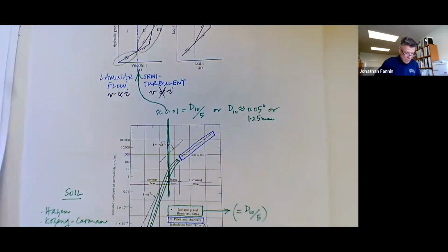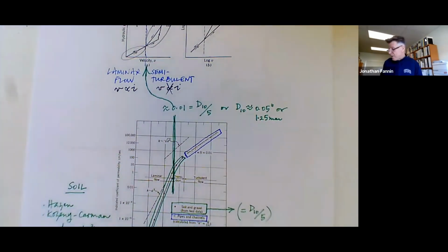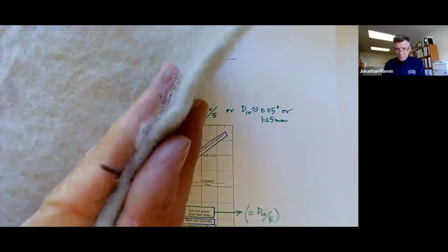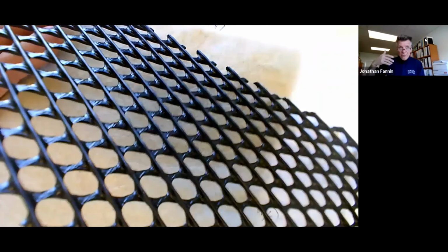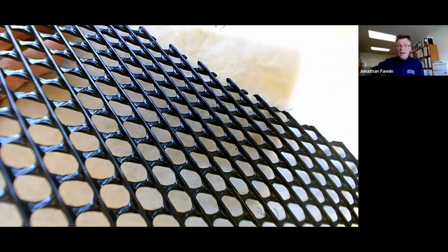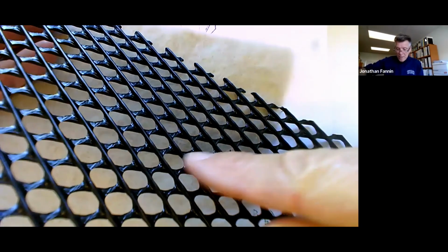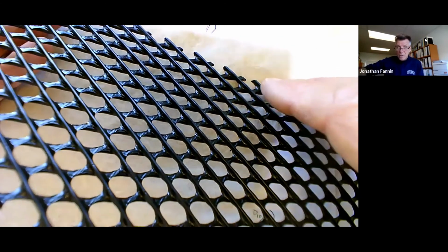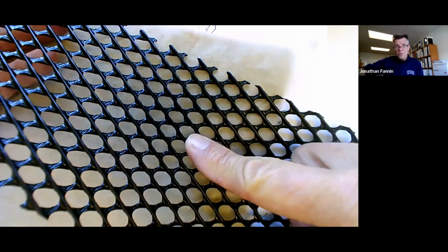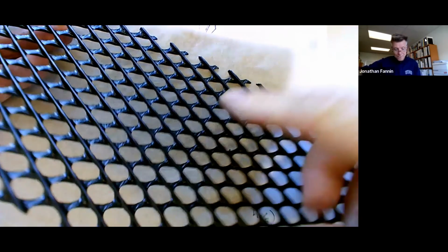To inform our appreciation of the flow regimes, and this will be either the flow regime in soil and across a geotextile filter, or the flow regime in something that's coarser, more gravel-like, maybe the flow regime here is no longer laminar. It might be semi-turbulent. That might be true for the geonet. It might also be true for gravels.